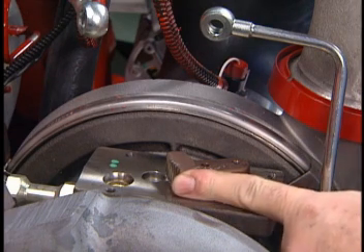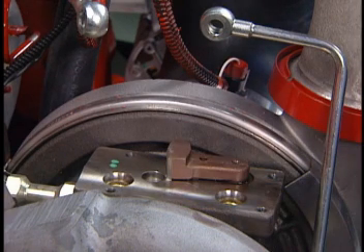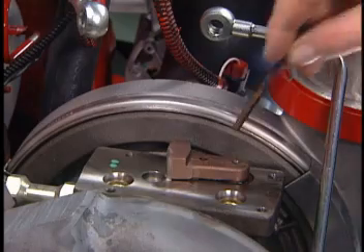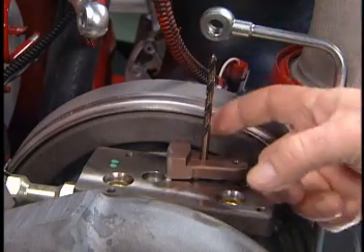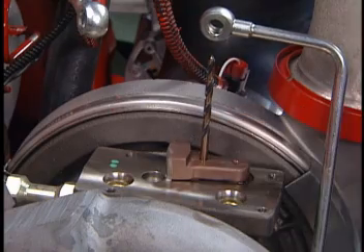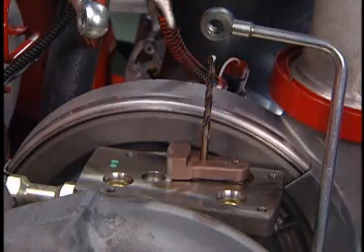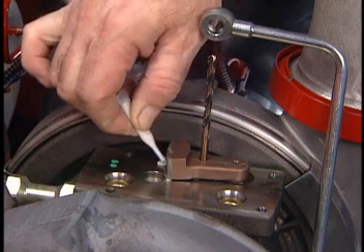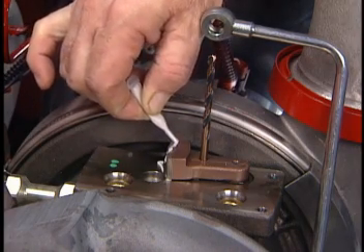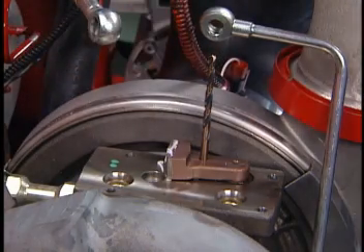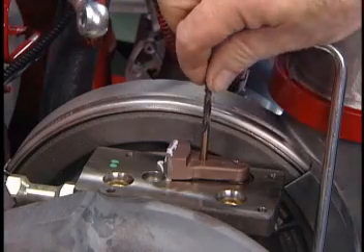Grasp the sector gear and rotate the sector gear toward the turbocharger compressor cover until the through hole lines up with the blind hole in the bearing housing. Use the alignment pin included in the service kit to make sure the sector gear is in the correct position prior to actuator installation. Coat the teeth on the sector gear with the grease packet supplied in the installation kit. It is critical for smooth, reliable operation of the actuator to use the full amount of the Cummins supplied grease. Remove the alignment pin.